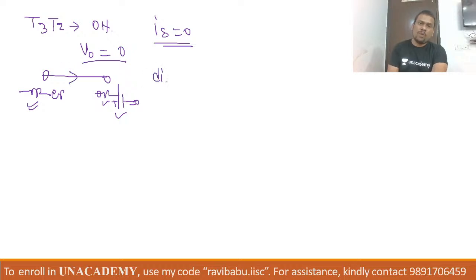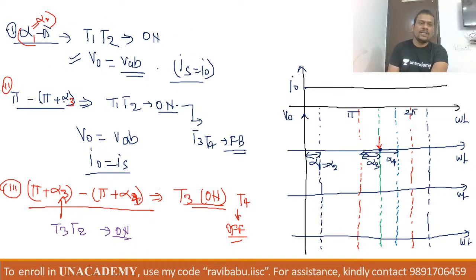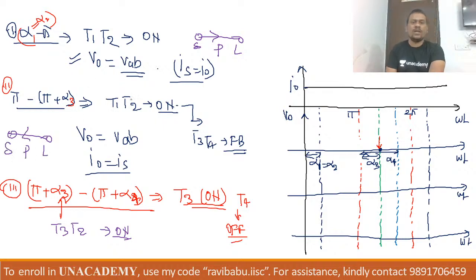So the slope of the inductor current, if your current is continuous, you can show like this, will be negative. Very nice. And here, in case 1, your power will flow from source to load. And in this situation, the second case, your power will flow from load to source. So this is the basic idea about the response of current. So you can write here positive, and here di by dt will be negative. So all things are mentioned.